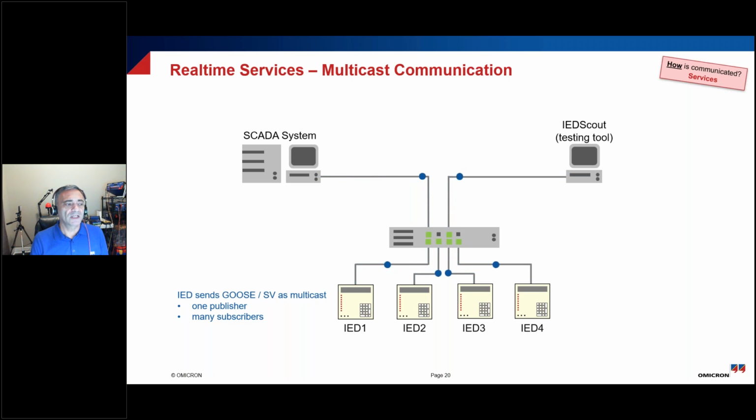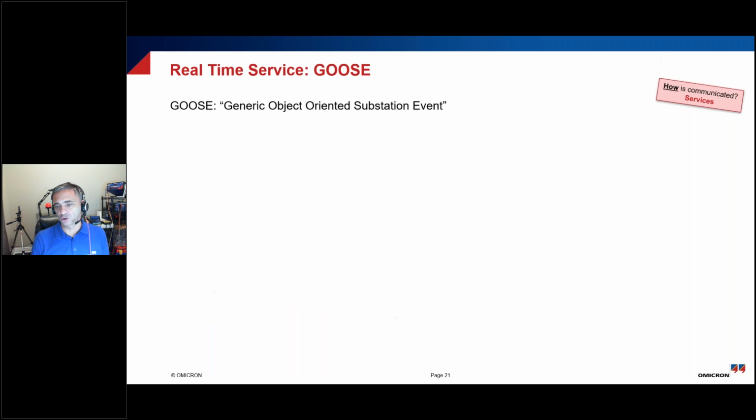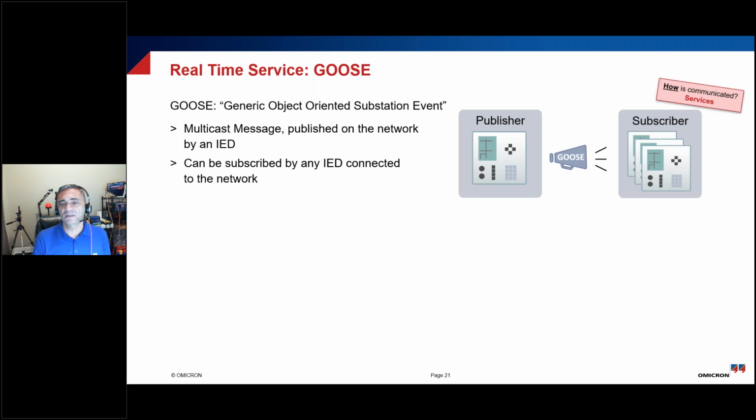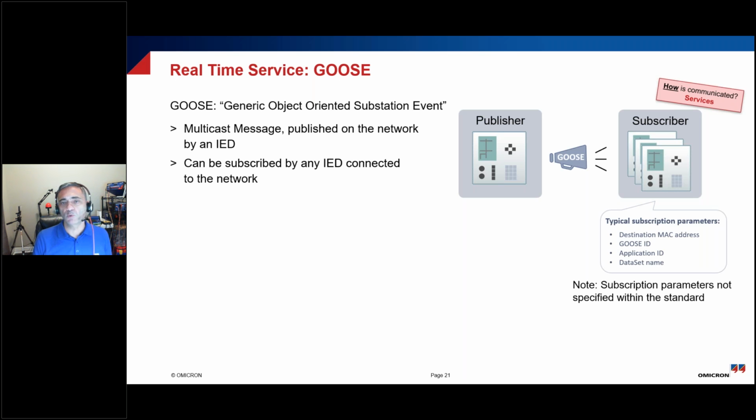So the other devices have the opportunity to bring that information in. Okay, it just transmits the information at power up, at any time the information changes, and in addition to that, just on an irregular time base. So as I said, it's called Generic Object-Oriented Substation Event Messaging, and it's just to get information from one device to many devices very, very quickly.